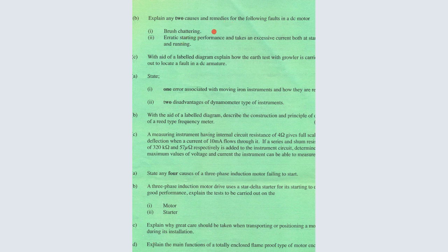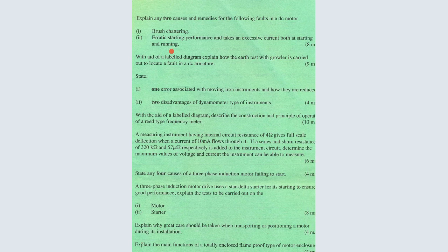So what are the remedies? Yes, you replace or you remove the dust. You remove the dirt or clean, or you replace the carbon brushes if they are totally spoiled. Good. Now the second one is erratic starting performance and takes an excessive current both at starting and at running.